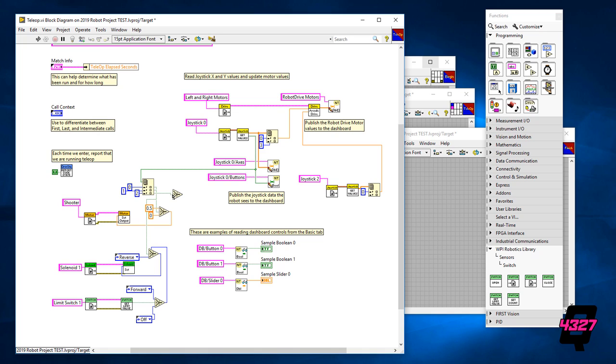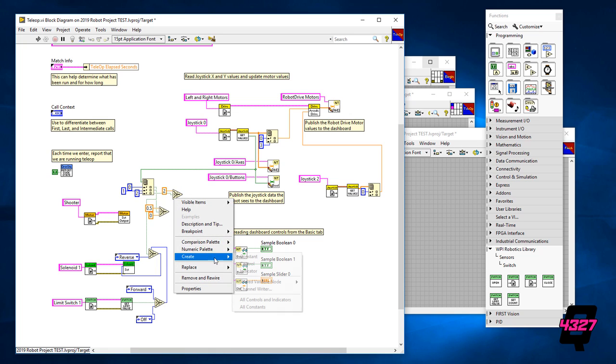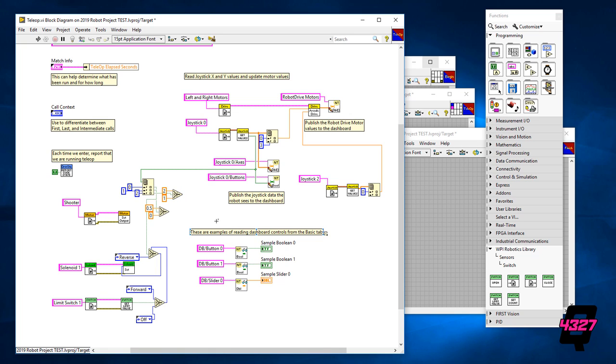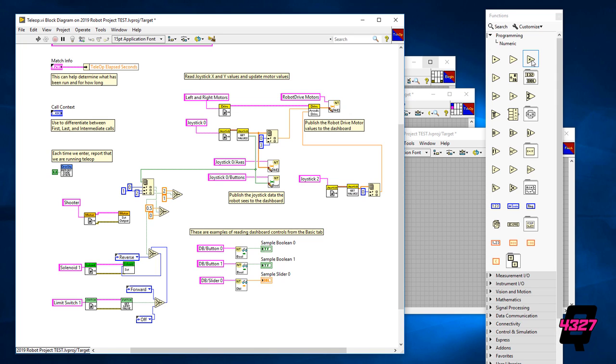Now we are going to add in a multiply gate to combine these 2 true-false gates. So, wire each output of the true-false gates into the left side of the multiply gate. Then wire the right side to the set input icon. By the logic, if you press button 0, you will get the 50% power like we did before. But if button 1 is pressed, the value from button 0 is now doubled. And then if button 1 is not pressed, then the value from button 0 is just multiplied by 1, which will make it remain the same as it was before.